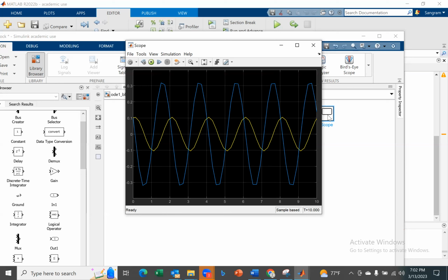Then we have to find out the potential energy. So we will find out the potential energy of the first link, and then the potential energy of the second link. At the end, we will write our Lagrangian as the total kinetic energy minus total potential energy. Everyone understood this? Then we will code that Lagrangian inside our MATLAB script.